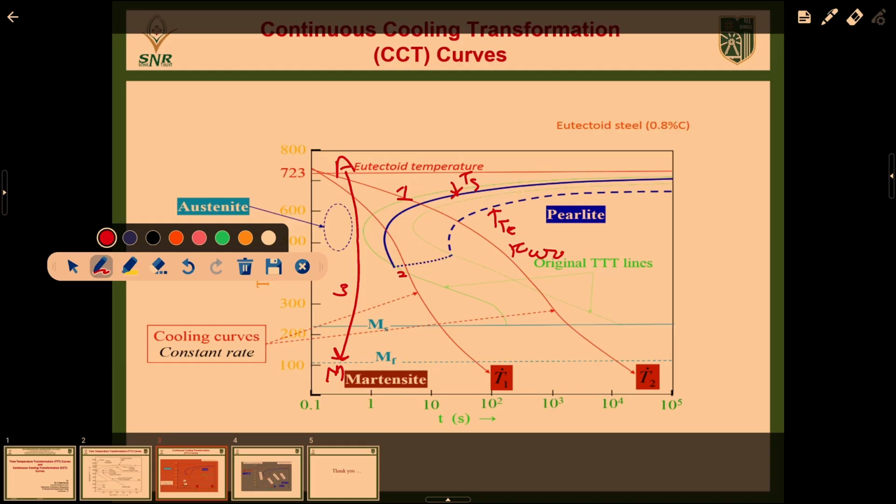If we are using furnace cooling, all of these things are happening. With water, sudden quenching, austenite is transformed to martensite. With furnace cooling, the atmosphere condition cools the entire material. Now we come to the second one.